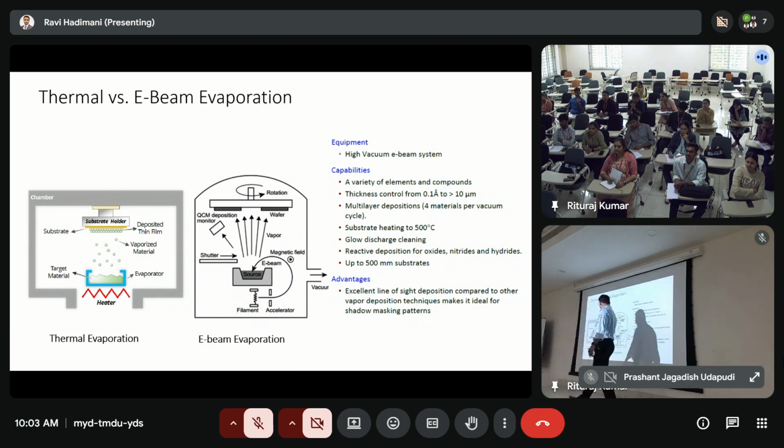And then there is e-beam evaporation. E is for electron, so you generate an electron beam from a filament, could be a tungsten filament. There are many ways to generate electrons. You also use magnets to direct where you want, so you direct it at the target. The target is what you want to deposit, for example, lithium or gold, platinum, or copper as electrodes, right?